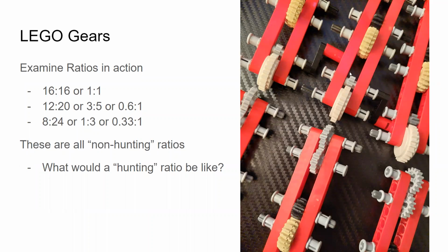Moving down my little apparatus here, we have a small gray gear with 8 teeth on it, and then a big white gear with 24. How many times does 8 go into 24? 3 times, right? So it would take 3 turns of that little gear to create 1 full turn of this big gear. So I got that ratio spelled out right here.